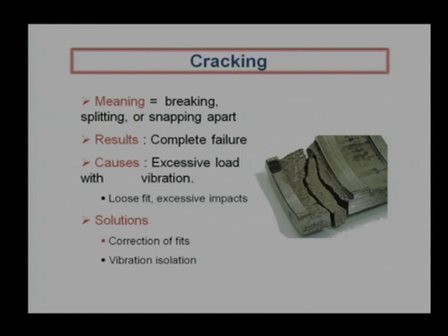Whenever we talk about fatigue, we talk about a large number of cycles, but this may happen even within 100 cycles. So, the cracking is the ultimate failure, and it may be instantaneous also. It is going to split the component. When the component is split, naturally it will not have any functionality; functionality will be 0. It is a complete failure, it cannot sustain, and we do not have any time left for its operation.